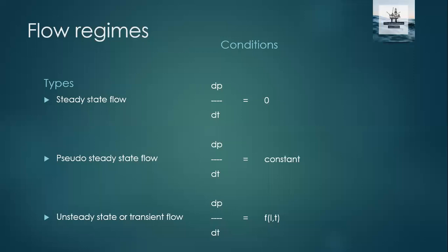When it comes to unsteady state flow, irrespective of any kind of drive mechanisms or artificial techniques, you can witness it automatically, immediately after drilling a well. Naturally, you open the well, you open the perforation, so fluid is expected to flow into the well, so there will be a disturbance, turbulence, or some kind of random disturbance near the perforations. In that way, unsteady state flow will be generated.